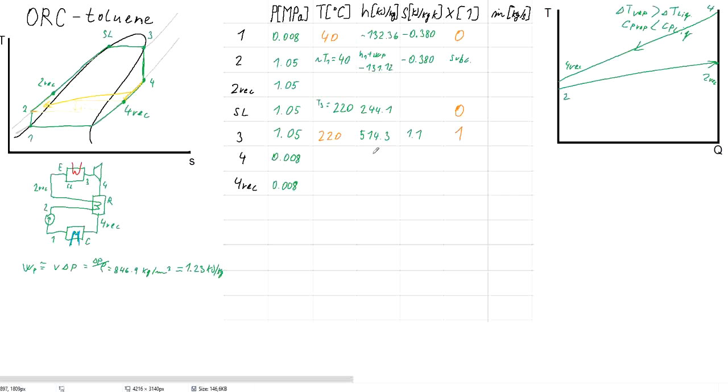Important for us will be the difference in enthalpy, where if we keep the same entropy over here and this low pressure, we will get the enthalpy value of 336.6, and the temperature for this point was 90.4 degrees C.